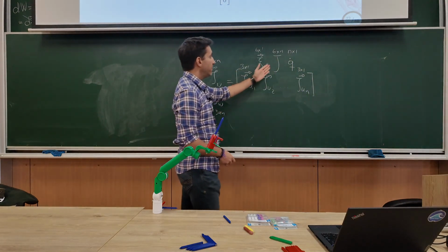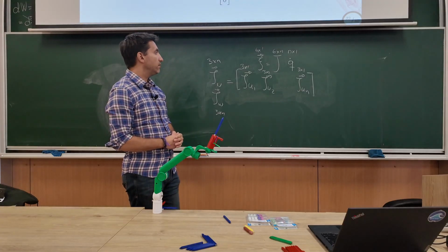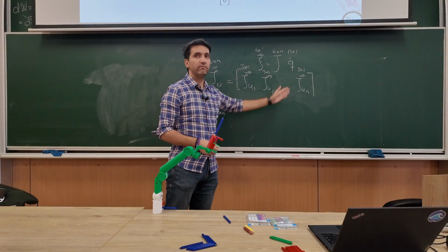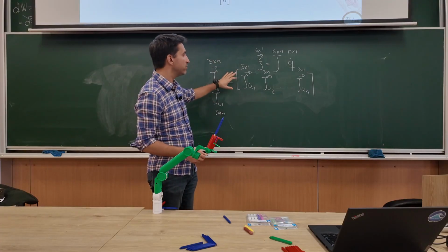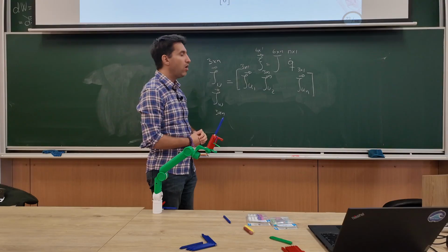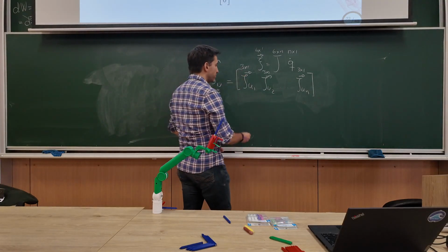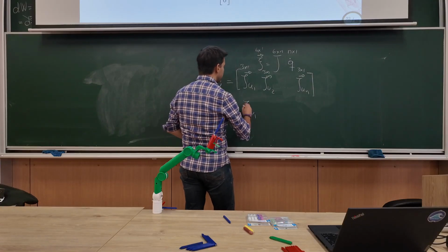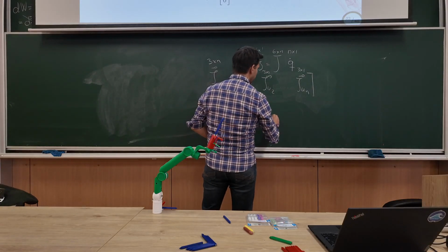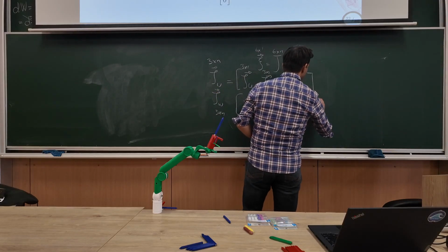So to calculate the overall Jacobian, we work column by column. We can do it separately, first for the linear Jacobian, then the angular, then put them together. Or I can calculate the whole linear and angular Jacobian for each joint. Let's say if I have them here, J omega n.